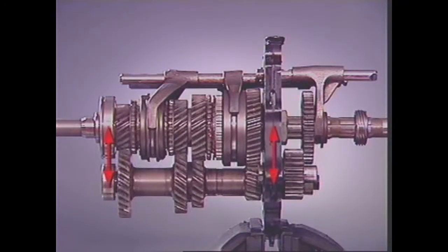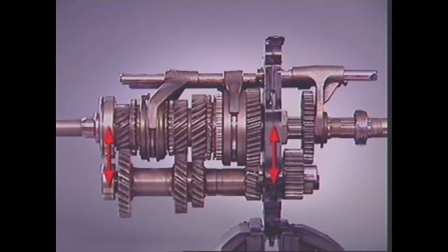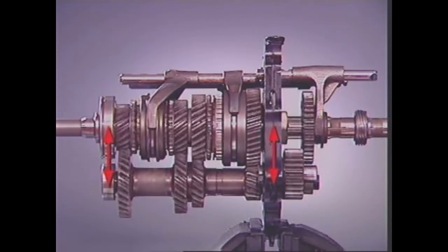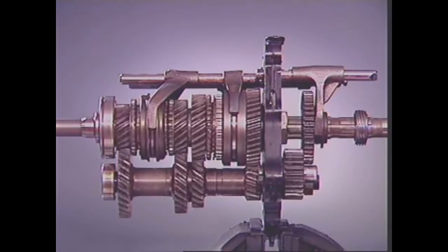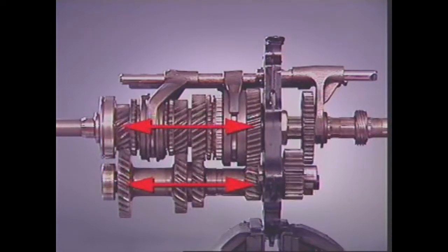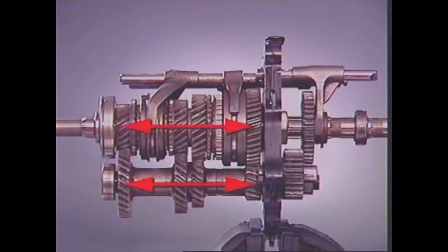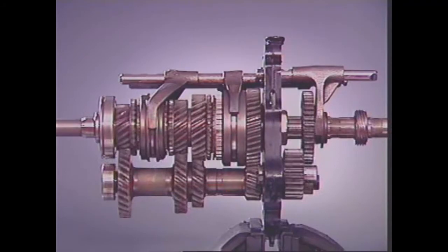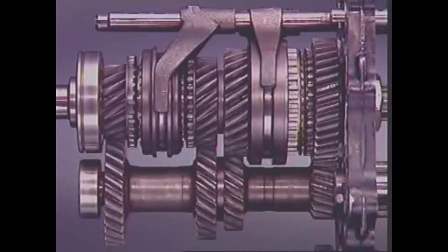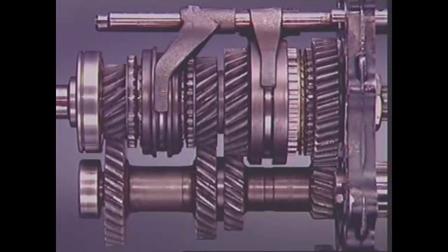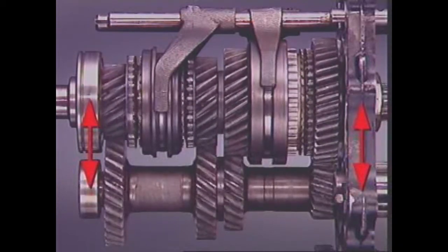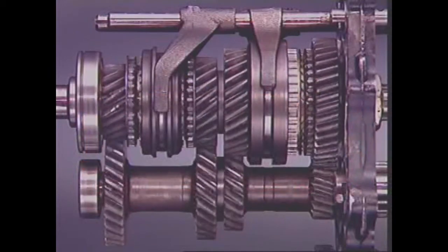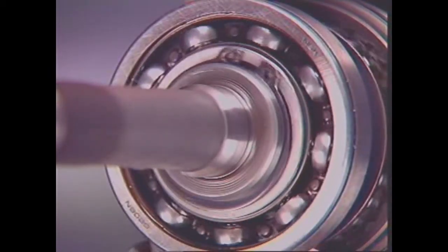Radial loads try to force the gears and shafts apart. The bearing, therefore, carries the load along its radius. Thrust loads are applied along the length of the components, so the bearing must cater for side thrusts. In many cases, these loads are combined, and some bearings designed for radial loads will also accept light thrust loads. This applies to most ball bearings.